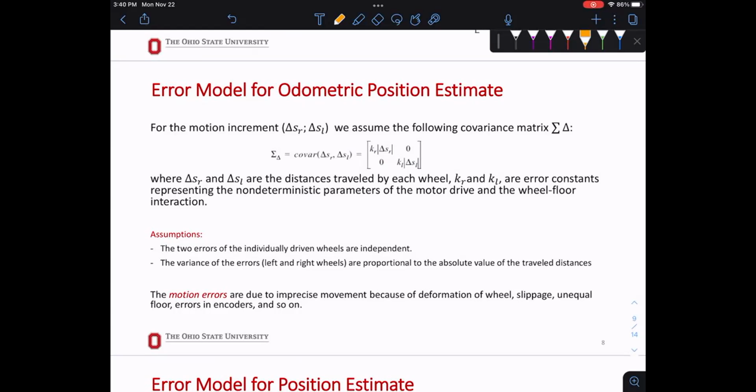So the distance B is fixed, right? Where the right and left wheels are, that length does not change. So you will measure it. Let's say it's supposed to be 2 meters, I don't know if 2 meters makes sense, but you measure 1.98. Okay, you put 1.98. You already calibrated. Things that you can calibrate and measure, you will do it, right? So it will fix itself right away when you measure that.